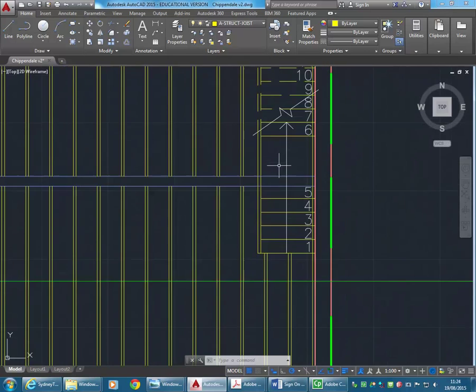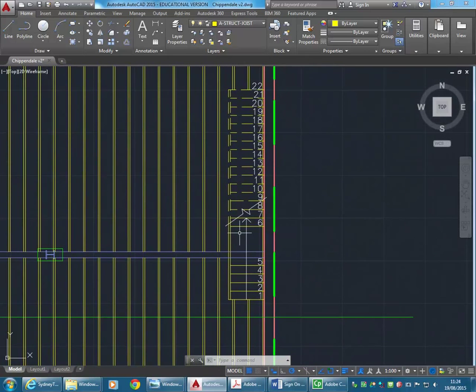For the stairs, well, it's a bit of a funny thing. Stairs in ceiling plans are always a bit of a debatable thing, because do you show them the way they look from the bottom or the way they look from above? And there's no right or wrong answer there. You definitely want to indicate their location. Strictly speaking, it should be the way they look from underneath. If it was opposite to that, you'd simply make the dashed line solid and solid like that. Kind of, but you're not really going to see this stair from below. You're going to see the stair for the next level from underneath.